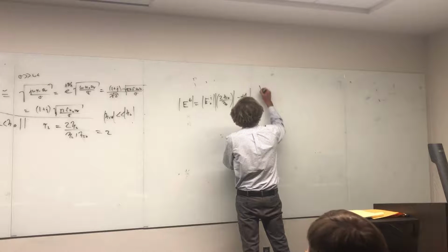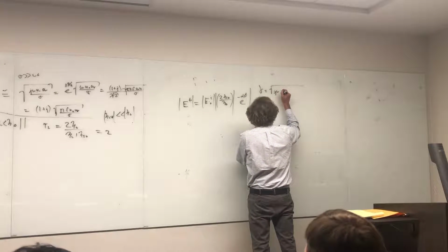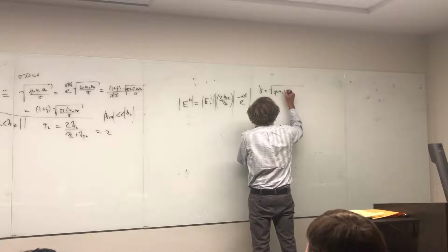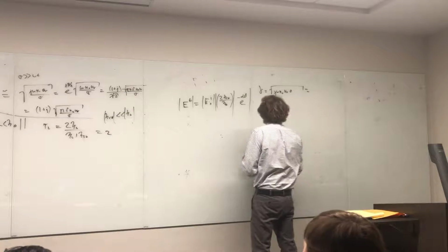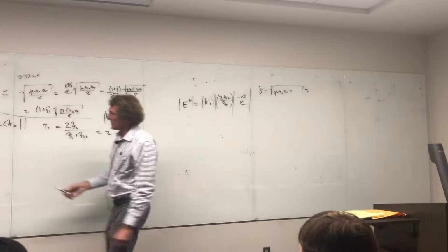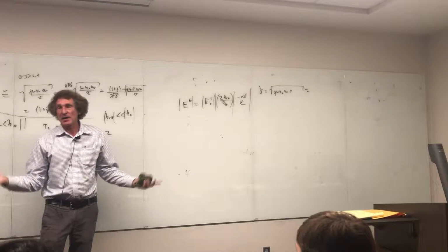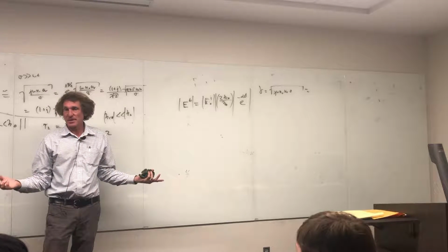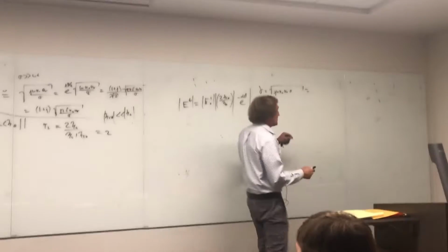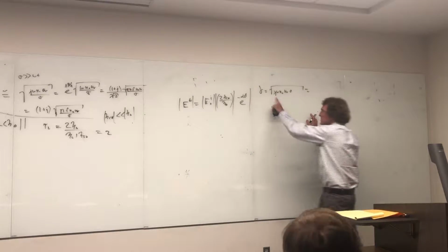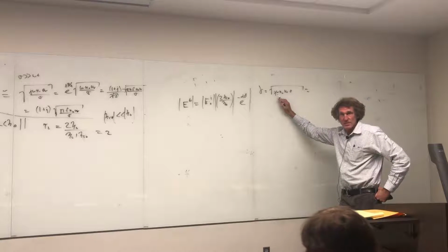Therefore, gamma will be equal to the square root of just j omega mu naught, mu relative, times sigma. I want to make sure I've gotten rid of this j omega epsilon. Everybody see that? You've got calculators. You can put it in if you want, but it's an insignificant thing. Doesn't matter. Well, if you look at this, now remember what I told you about the square root of j. That's actually equal to 1 plus j over the square root of 2.